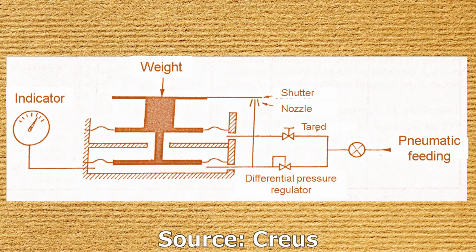Pneumatic load cells consist of a pneumatic force balance load transmitter, in which the weight placed on the load platform is compared with the effort exerted by a diaphragm fed at an adjustable set pressure. The system adopts a balanced position thanks to the nozzle shutter assembly and the feedback chamber of the transmitter. The air pressure reached in this chamber indicates the weight.